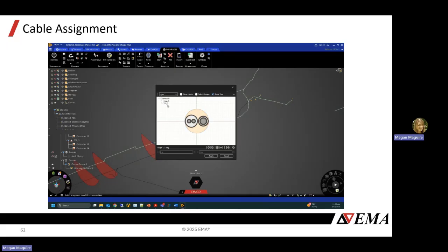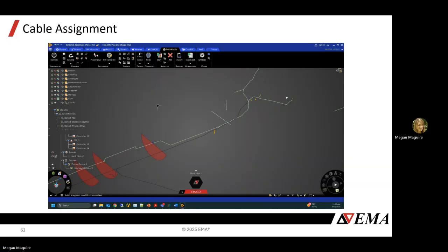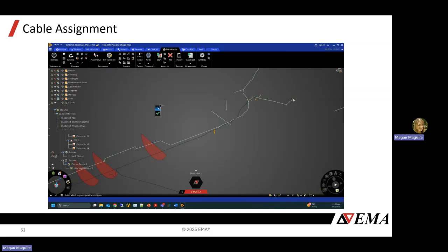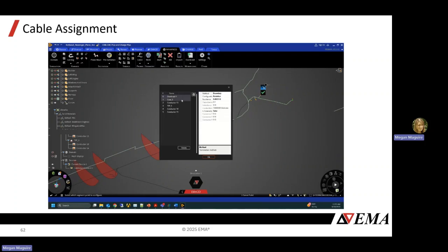Then you can inspect a single segment and see where your TSP is located in that cross section. There is also an interaction point tool that you can use. For things like circuit terminations, you can find custom junctions or probes at those locations. You can also go into bulk edit terminations, where you can look at everything that terminates at that point.